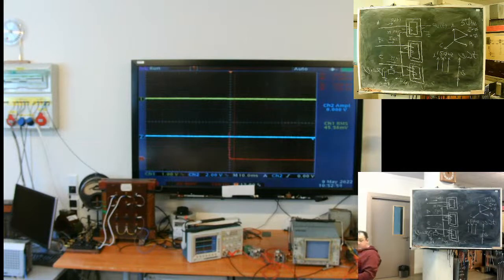But at night, when the network is not loaded, if the voltage control system is not working well, voltage rises, the amount of third harmonic in the magnetizing current rises, and we will see overvoltage.